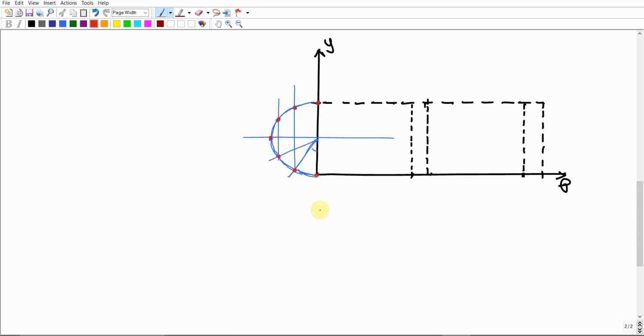Then you're going to give them numbers starting from 0. Why is this the 0? Because this is our start point. We're going to start from here and go up. We're going to rise starting from this point. So this is the start point, this is the 0 point. This is going to be point 1, this is point 2, point 3, 4, 5 and 6, following the same procedure that we explained in the previous video regarding the generation of the simple harmonic motion.